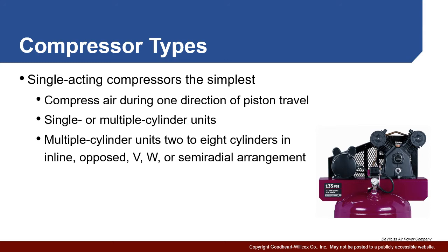Now, when you think about single acting, keep in mind you oftentimes will see multiple cylinders involved. So, for example, if you take a look here, you see two cylinders over here on the right. That doesn't mean that it's double acting. There's actually two single acting cylinders, but they're multiple stages.